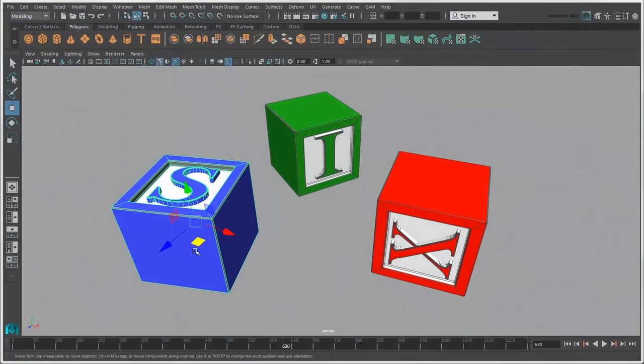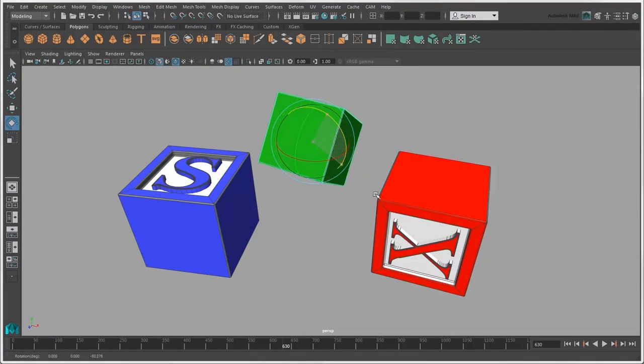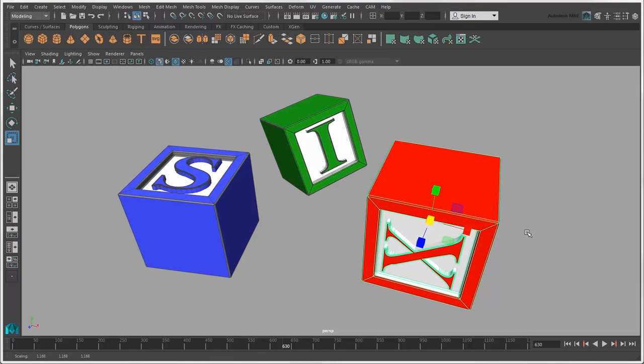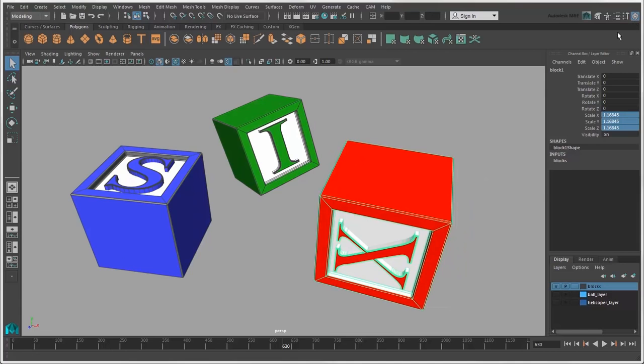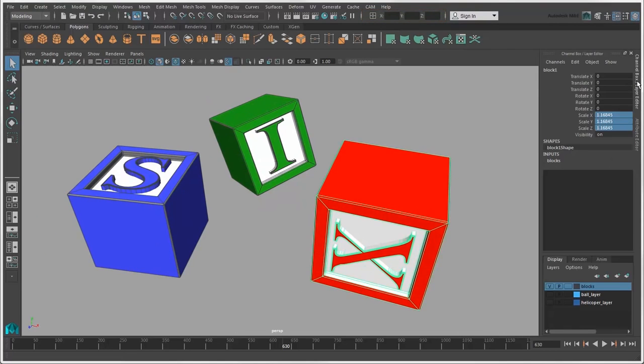When you're transforming objects and components, you often use the manipulators for the Move, Rotate, and Scale tools because they're interactive. But sometimes you need to use exact values, which are tricky to get with the manipulators. There are a few tools in Maya that give you this precision: the channel box, the attribute editor, and the input box on the status line. The channel box is the most commonly used tool for doing this, and also lets you easily key these values if you want to animate them.